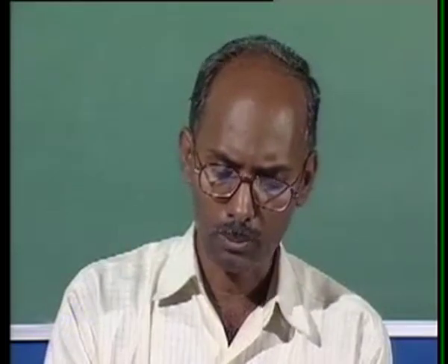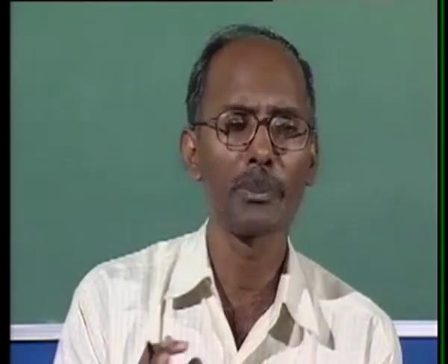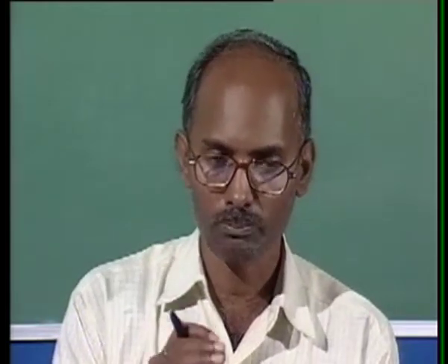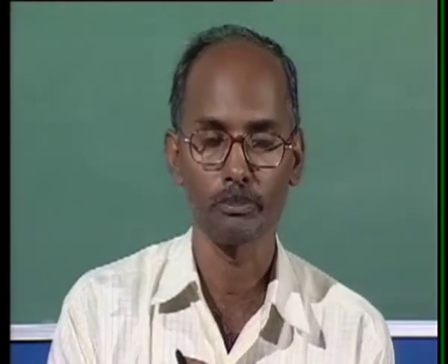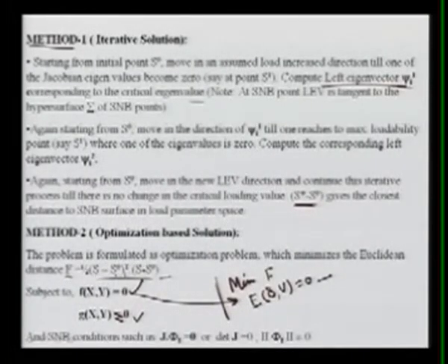Here this problem is highly nonlinear. So the selection of the method matters; although you must be knowing there are so many optimization methods even in nonlinear, some have inherent problems, and then you have to choose carefully. Also the initial guess is very, very important. So we start from S naught, find some initial guess, and then we can get the optimal solution. So at that point, at the saddle node condition, the Jacobian determinant becomes 0.